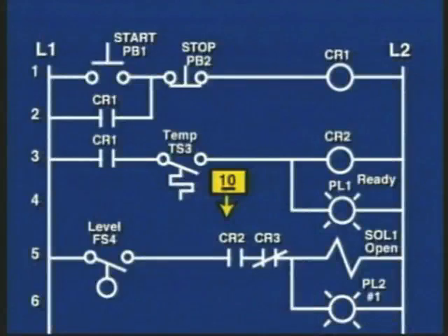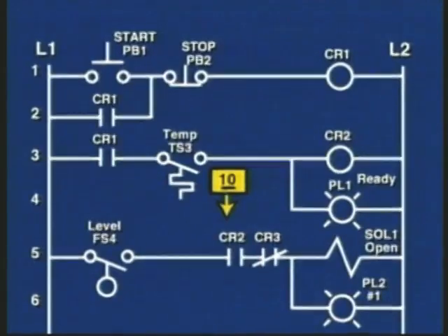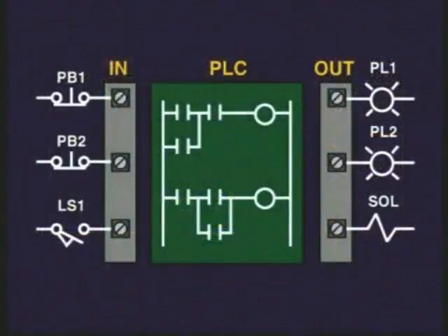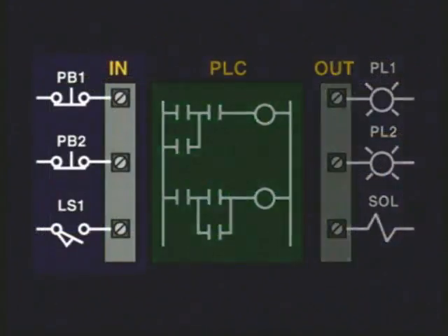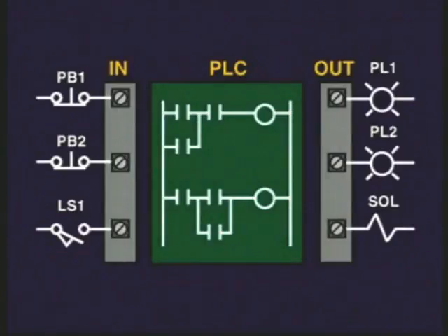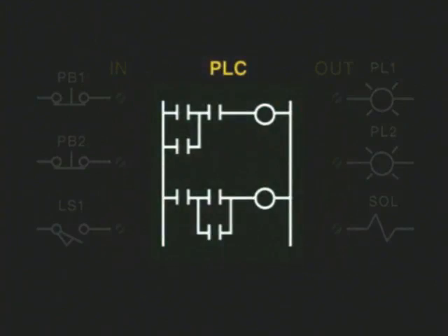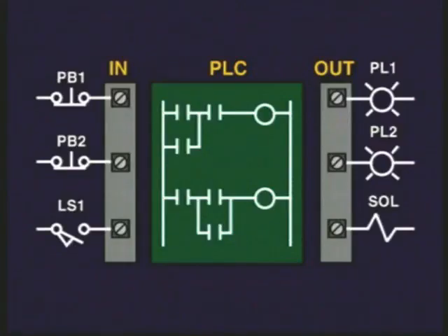The ladder diagram has been, and will be to a certain extent, the traditional way of representing electrical sequences of operations. In hardwired circuits, the electrical wiring is connected from one device to another according to a logic or sequence of operation. In a PLC, the devices are connected to the input interfaces, while the outputs are connected to the output interface. The actual wiring of the components is done electronically inside the PLC through the control program using the familiar ladder diagram symbols.